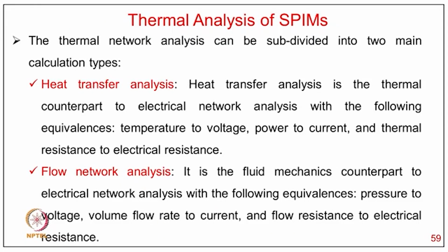Then there is of course the computation used for thermal analysis of single phase induction motors. Thermal network analysis can be subdivided into two main calculation types. Heat transfer analysis is the thermal counterpart to electrical network analysis with the following equivalences: temperature to voltage, power to current, and thermal resistance to electrical resistance. And flow network analysis is the fluid mechanics counterpart to electrical network analysis with the following equivalences: pressure to voltage, volume flow rate to current, and flow resistance to electrical resistance.